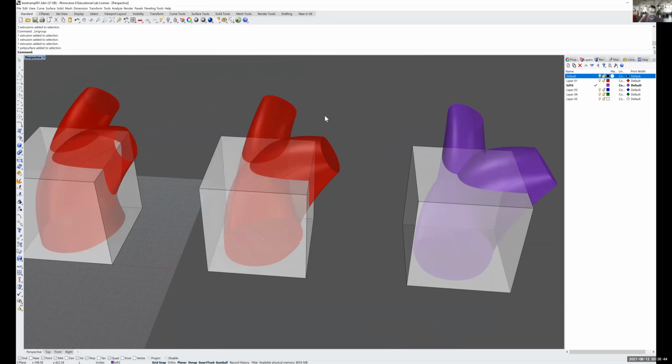Let me try that again. So I just click and type cap, right? Yeah, you just type cap. Or do I? You select it, and if they're planar, they should get capped and it should become a solid at the end. Okay, so I have to type cap first, then select, then enter. Yep. Okay, yeah, that capped worked.